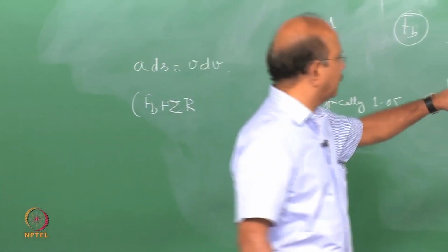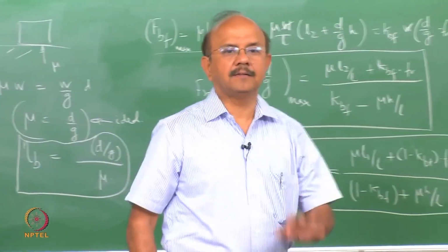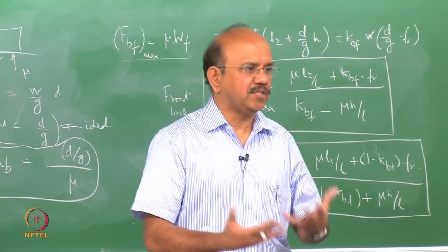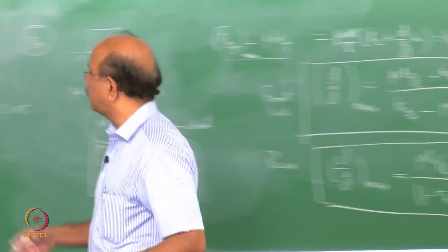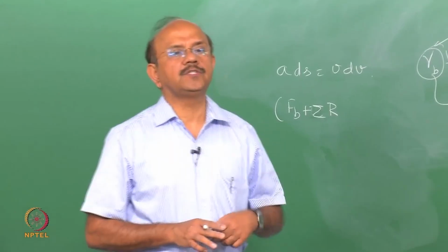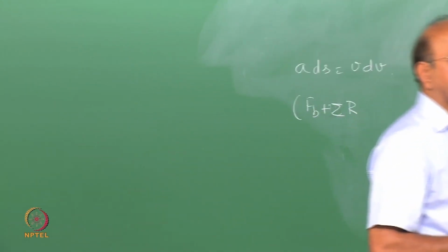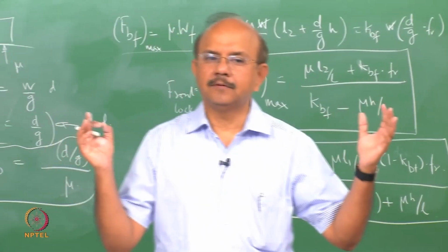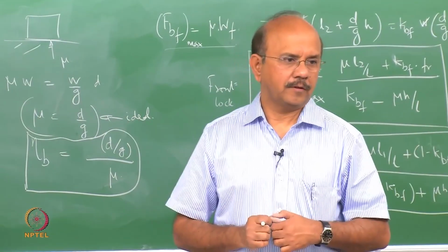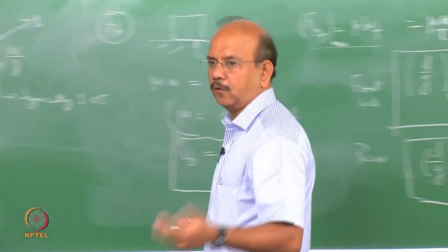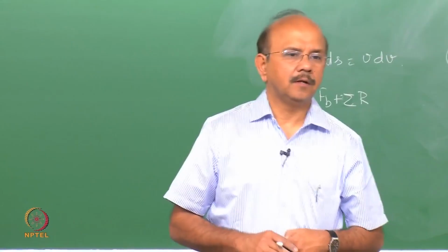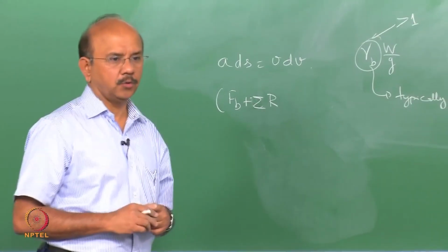Please remember that in the previous expressions I had left out certain resistances just to make it easier for you to understand, but in actuality I have to introduce all the other resistances as well, which includes the gradient and the aerodynamic forces. Okay? So, we need to include not only rolling resistance, we have to include aerodynamic forces, we need to include the gradient and so on, right.